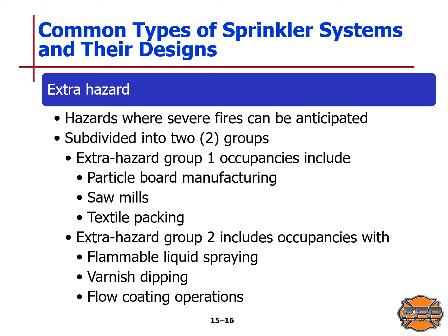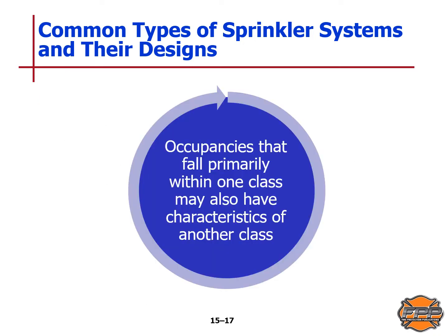Extra hazard group 2 includes occupancies with flammable liquid spraying, varnish dipping, and coating operations. Occupancies that fall primarily within one class may also have characteristics of another class.